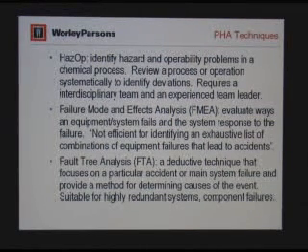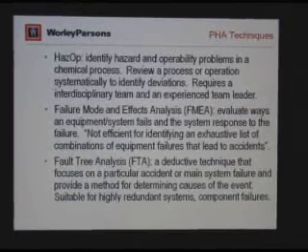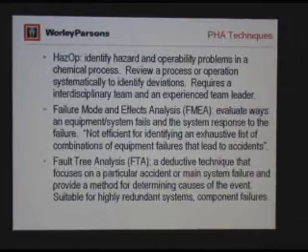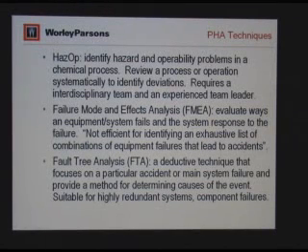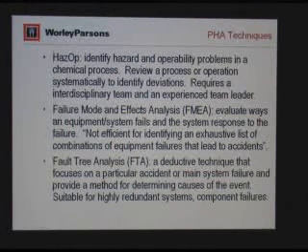And I guess the advantage of the HAZOP is you have to go through a set of guide words and also parameters, so it avoids possible overlooking of some of the problems. And also you have a team from all disciplines, and different disciplines have different concerns, so you can see the problem from different views. And that's why this is a preferred process.